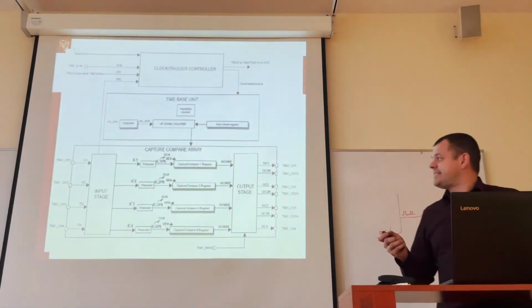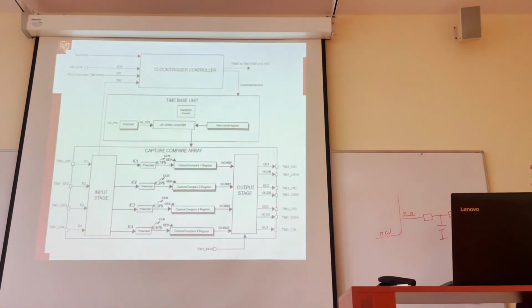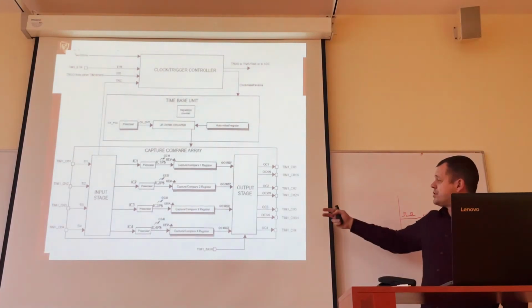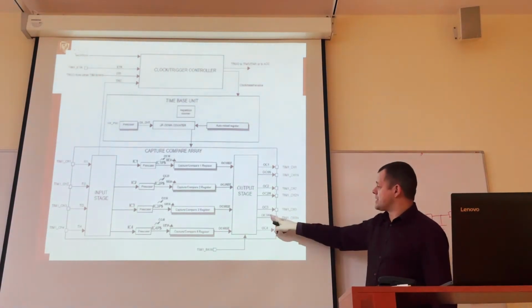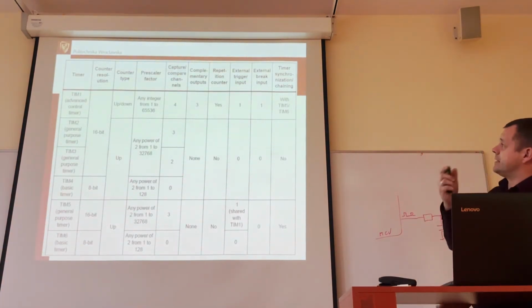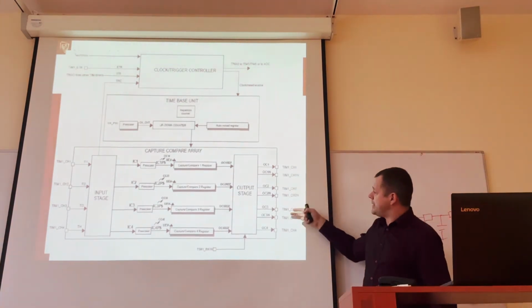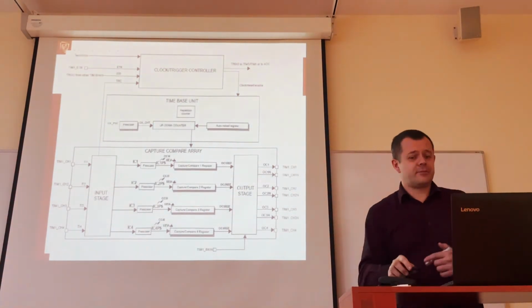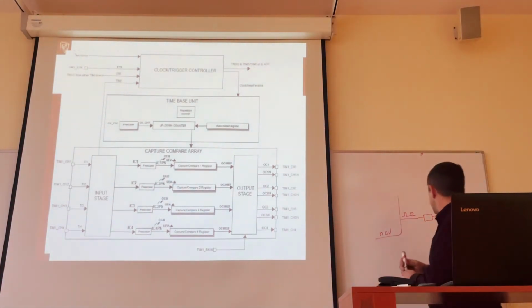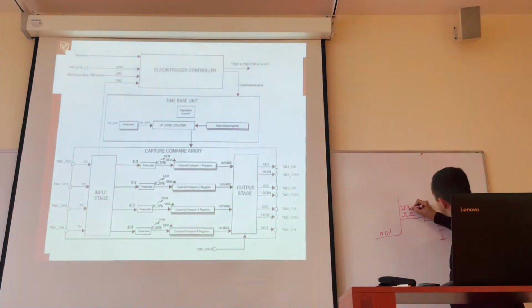That's also the reason why DACs, digital to analog converters, although available in microcontrollers, are not very popular. Here we also have something additional in this microcontroller: three channels which are negated, because N stands for negated, or they are called complementary in English. So we have complementary outputs. Why the complementary outputs? Who knows? What's the sense? Complementary means we have one signal this way, the second signal this way. This is negated. Positive, negative signal.